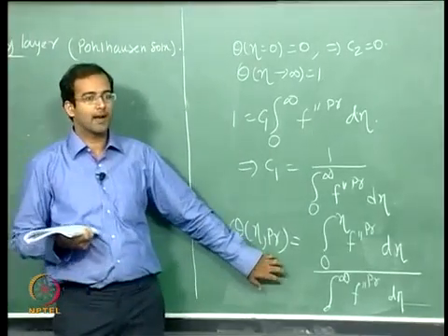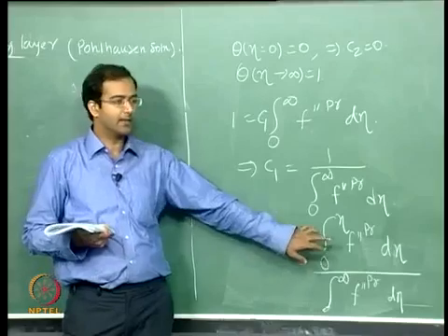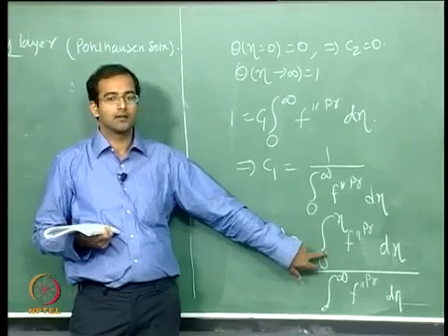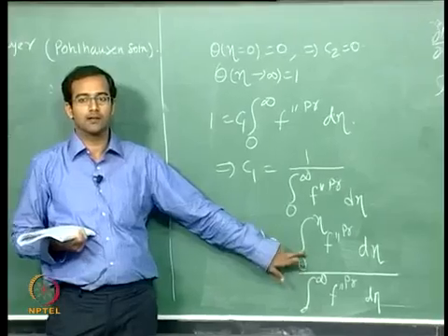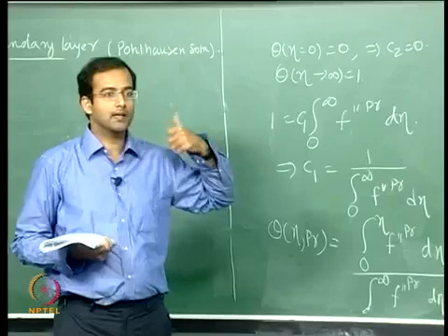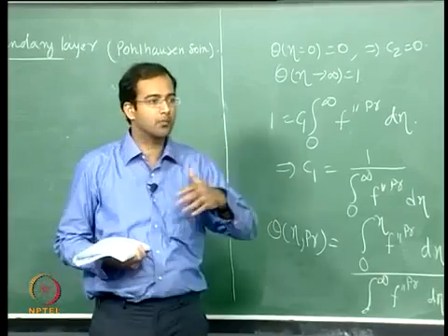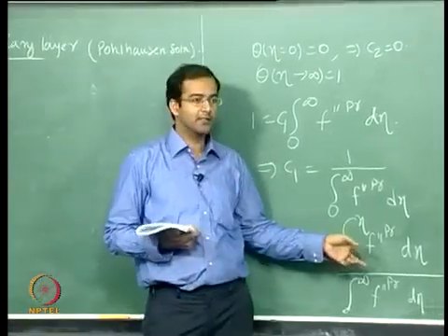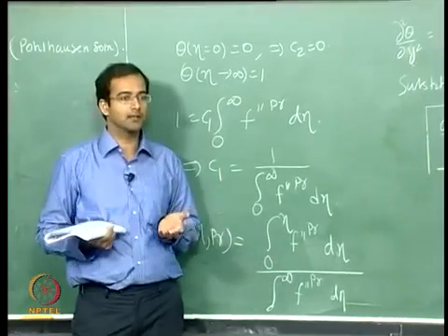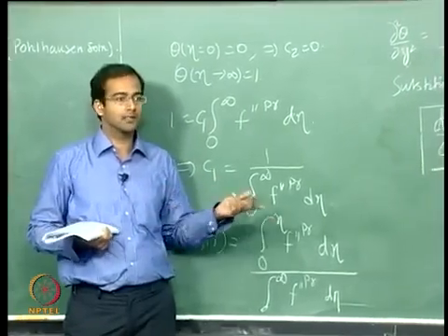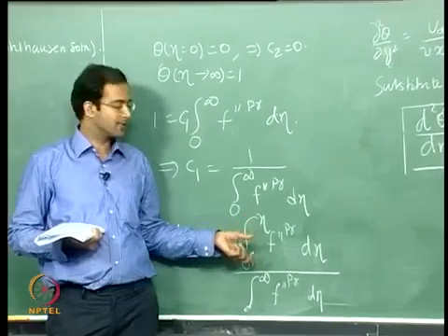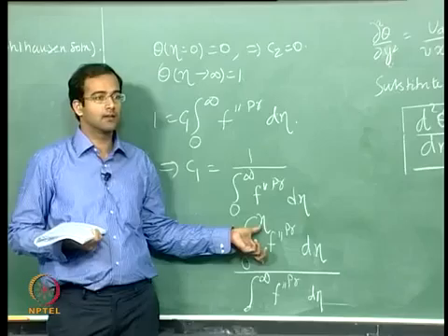Although this looks like an analytical solution, finally the f you are getting is not a continuous function, right? What you got from the Blasius solution numerically was for discrete points. Therefore f is available only for discrete points. So what you can do is a curve fitting, make a continuous function out of it and integrate it here. Even the integration has to be done numerically.